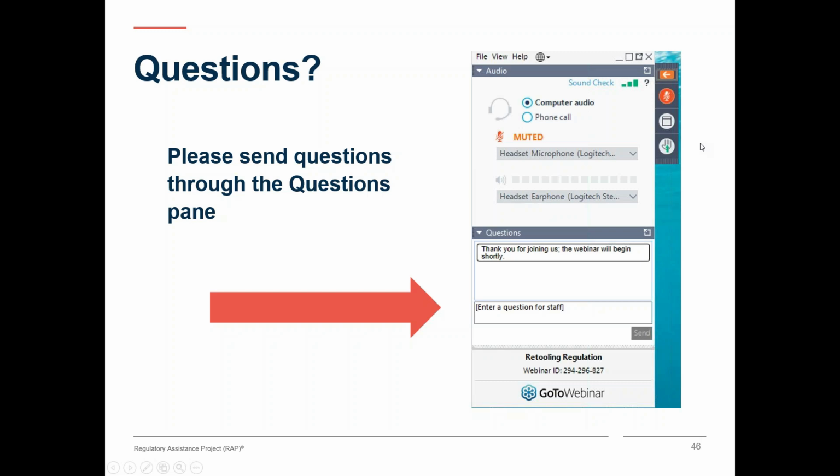It's a great way of getting the relevant data. And I've worked with a number of utilities that have stupendous data from their AMI systems, and it's showing things that are very different from what we got from load sampling in the past. And one thing it showed is that specific areas of the service territory that have high, for example, air conditioning saturation, are imposing peak loads that are at different times and different magnitudes than other parts of the service territory that may have less in the way of central air conditioning. And that can be the inland versus coastal areas in California. It can be low income versus suburban service territories for some other utilities.